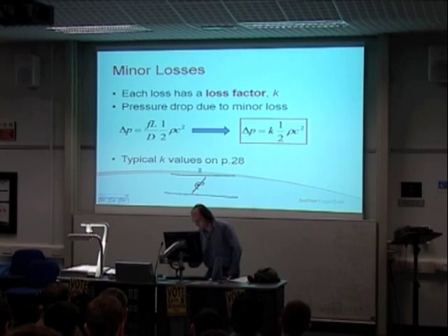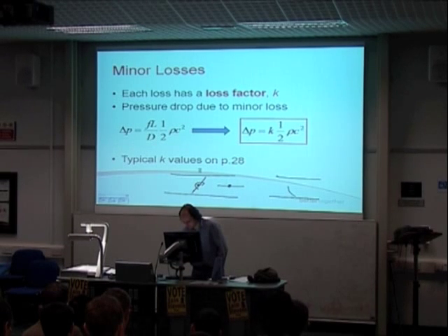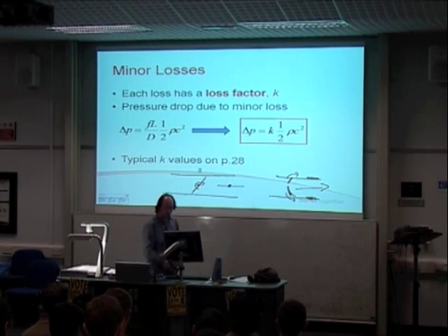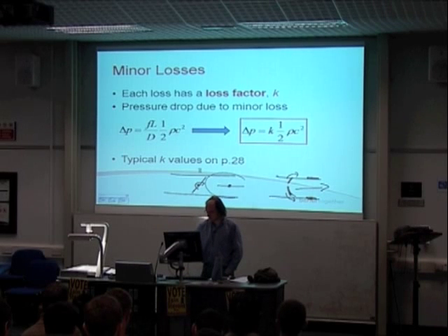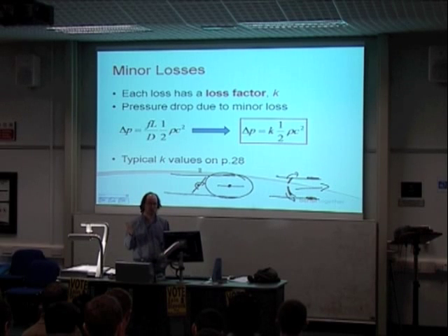And of course, when the valve is fully open, okay, there's still going to be a pressure drop because you've still got something in the system, which is why, if you look at Formula 1 cars, okay, they've got valves that operate at the side. And so it's like this, okay, let's go like that. Okay, and when the valve is fully open, these rotate in to the walls, and you end up with nothing in the pipe, okay? And obviously you get full flow through there. There's no pressure drop associated with the wide open throttle in a Formula 1 car engine, okay? But with your car engine, petrol engines, you'll get a pressure drop just because there's a throttle valve, okay?